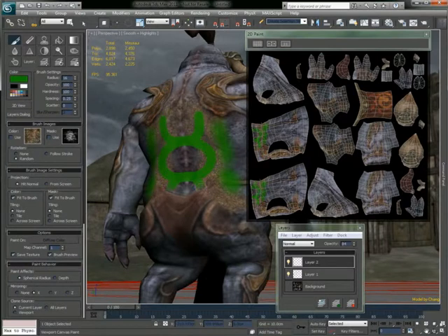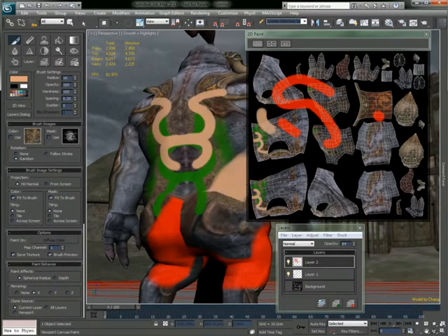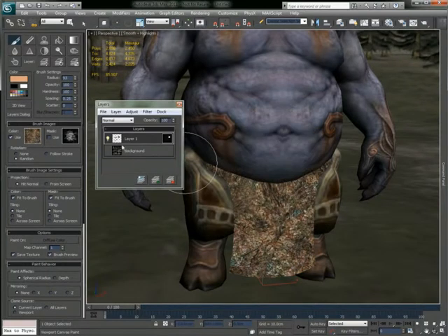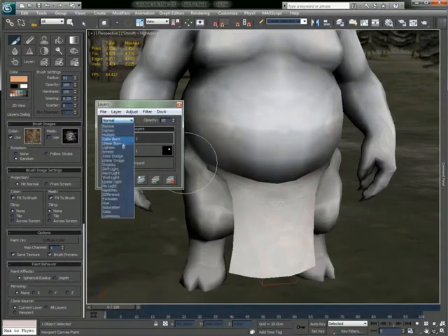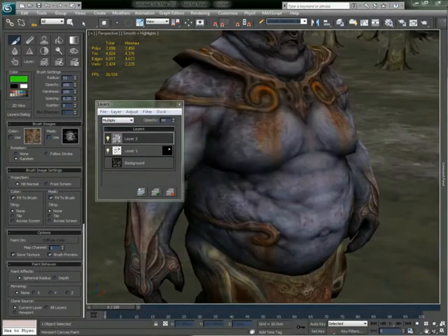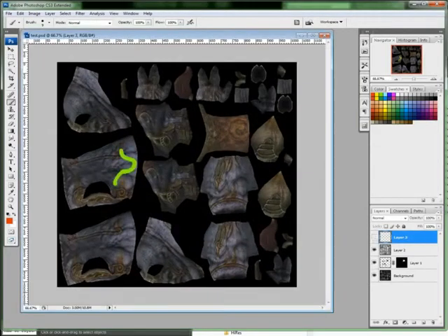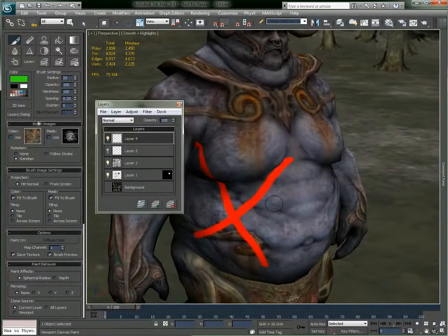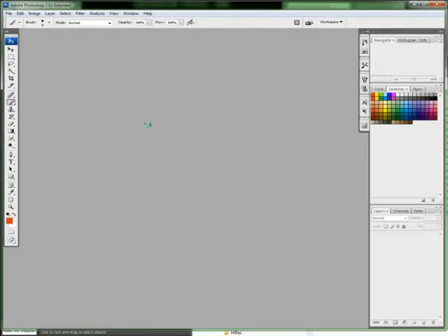While working with Viewport Canvas in 3ds Max, users can either paint in an unwrapped 2D layout or directly on the surface of the selected 3D model. Layers created using 3ds Max's Viewport Canvas can also incorporate masking alpha channels, layer opacity, and blending modes, also known as transfer modes. Speaking of Photoshop, all of this work done in the Viewport Canvas can be saved to standard PSD documents. These can easily be round-tripped between concurrent running sessions of 3ds Max and applications such as Photoshop that can work with PSD files.